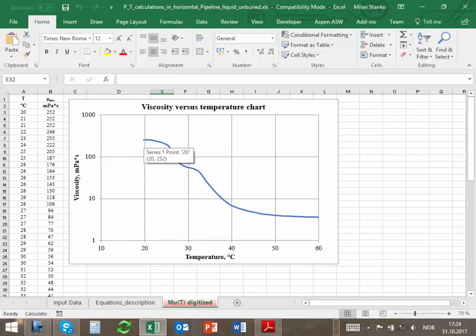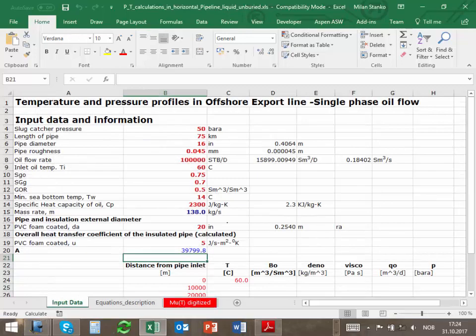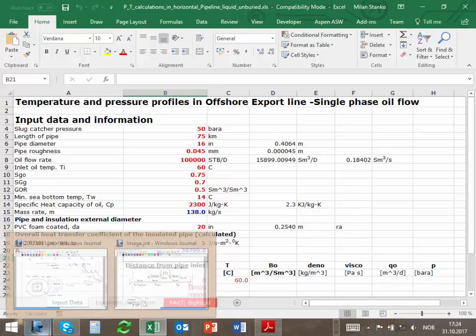which is very high. For a typical oil, it might be something between 1 and 8, or 1 and 4. When we are already talking between 50 and 100, this is a highly viscous fluid. And when we go to 2000 centipoise, that's just too much. It will create a huge pressure drop.